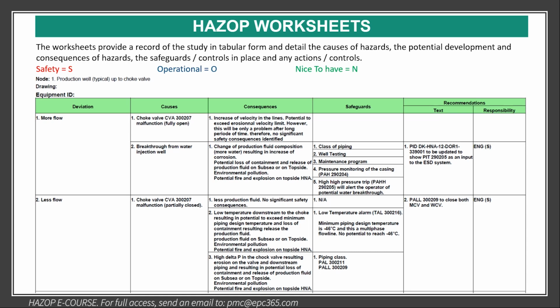And here, for example, we write the engineering, and it is a safety thing. When we write the safety, normally all the things relevant to safety, each phase of the process should be closed before going to the next phase of the project. And then we will talk about the Hazop closeout report. So this is S, and this has to be defined and closed during the phase for safety. We are in FEED, we have to close it and then go to the detailed design.